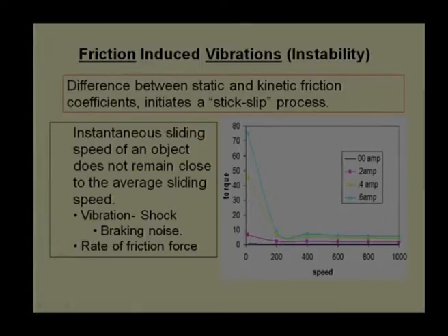We use a magnetorheological liquid as a brake material. The good thing about MR fluid, or magnetorheological fluid, is that it gets solidified in just a few milliseconds, and due to this solidification, the coefficient of friction increases significantly. We say the coefficient of friction from 0.1 can reach 0.6 in 10 milliseconds, which gives a braking torque, or which gives the resistance against a movement. But what is the problem with this?